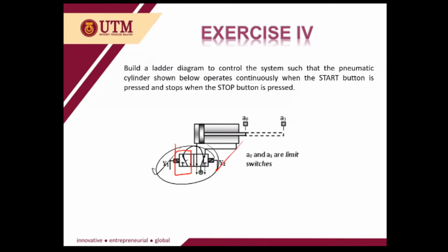Y2 will only switch the valve to its right position. Remember, Y1 switches to the left position, Y2 switches back to the right position. It's not like you have a spring return valve, spring actuation on the right, where if you deactivate Y1, it will kick back the valve immediately to its initial position.